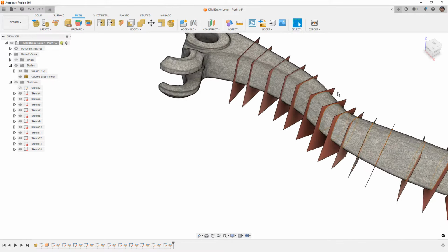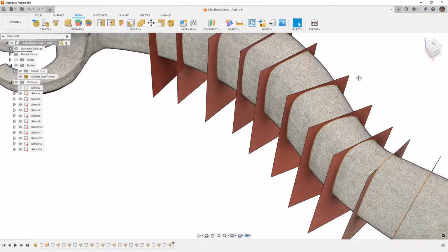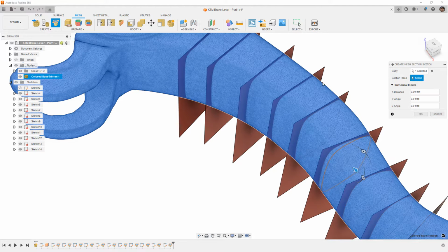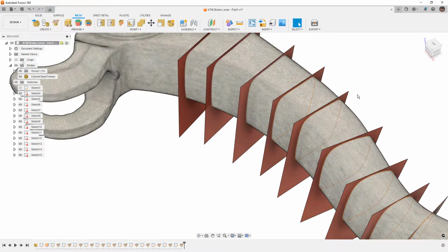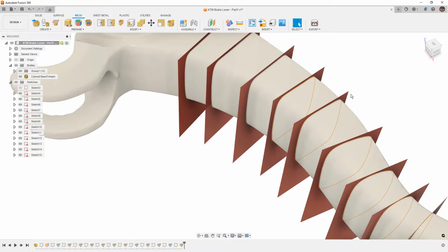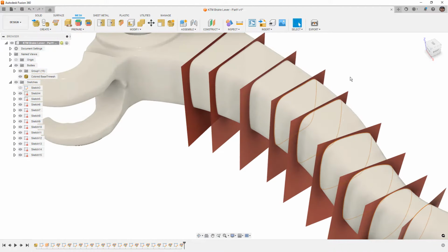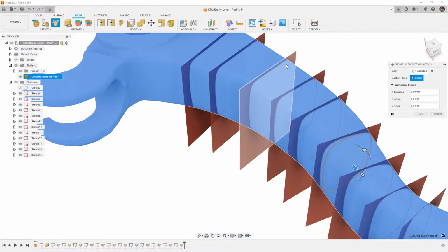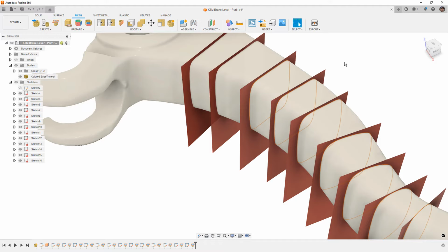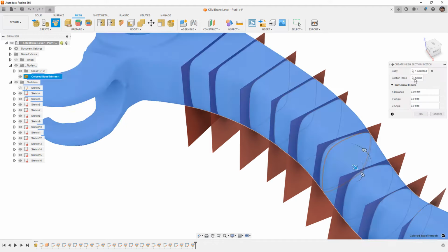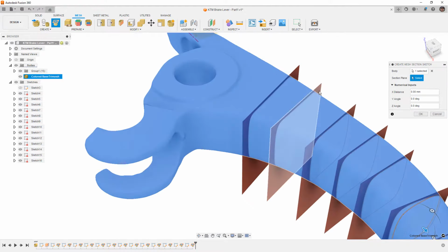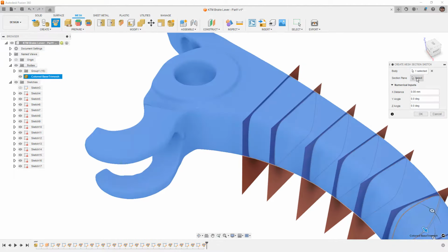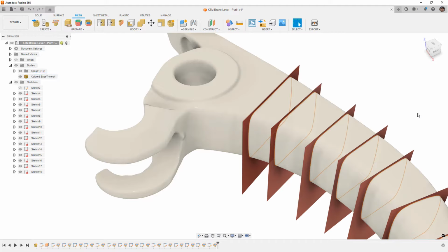It can be kind of tricky to see if you are getting all the curves. So every once in a while, you can think about changing the color or zooming in. You can also use Control and 4 to hide the edges. When you have a mesh, those edges really make a huge difference just visually. So doing this by hiding the edges can be a little bit quicker. And one more to go. Right click, repeat, select the mesh, and there we go.